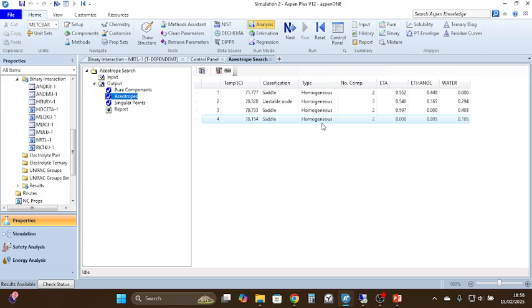To speak specifically, the system separates into two distinct phases at equilibrium, that is, at the operating conditions where the azeotropes are formed. An example is the water, ethanol, and benzene mixture. The previous one was ethanol, water, and methanol, but this one is a water, ethanol, and benzene mixture. They form a heterogeneous azeotrope.